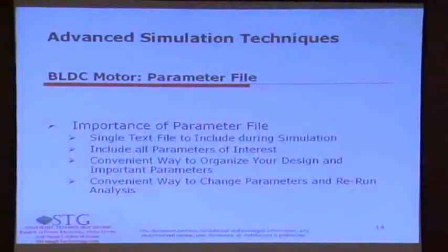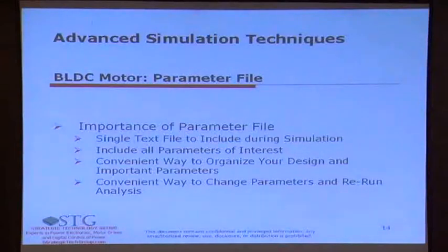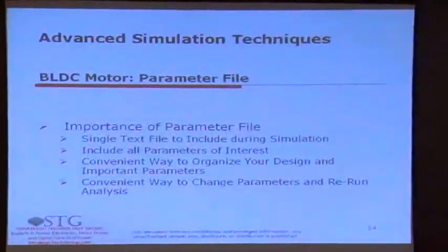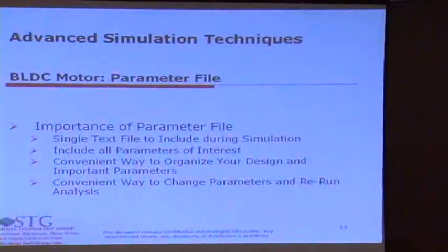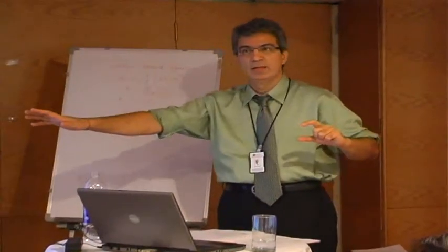Now, we like the parameter file quite a bit because it allows ease in simulating. You can also put all your parameters on your schematics in PSpice. But we like to put it as a separate file, number one, because it can be used in other Spice programs.